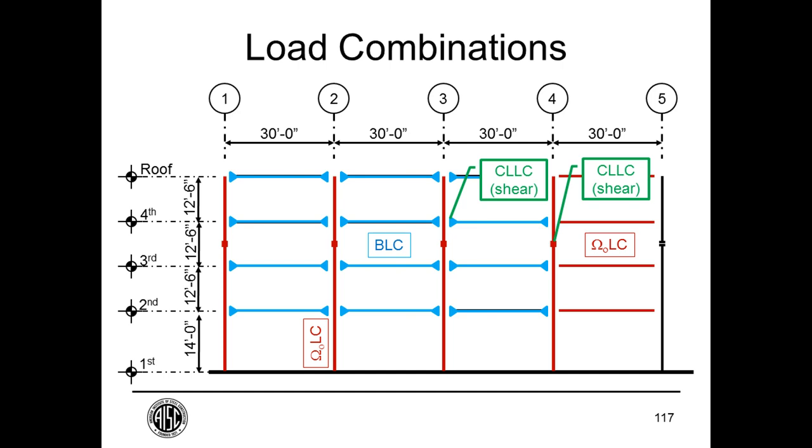And at line 4, all of those shears are pushing the column down, so there will be compression on that base plate. So in order to make sure the column has adequate strength for the combination of, say, that compression plus the flexure associated with the moment frame behavior, we use the amplified load because we expect each of those beams to yield and strain harden and to develop forces that are much larger than the base shear forces that they were designed for.